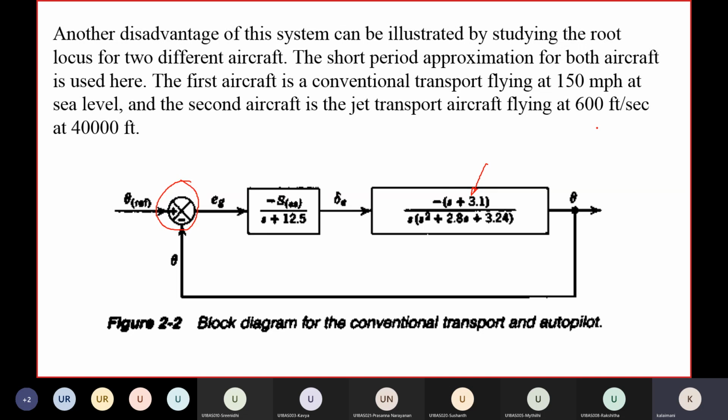If there is any change in the heading reference, then we can use the rudder to counteract it. Therefore, in this case we are using a directional gyro instead of a vertical gyro. Whenever any changes occur, how the displacement autopilot counteracts the effect, we will discuss in subsequent lectures.